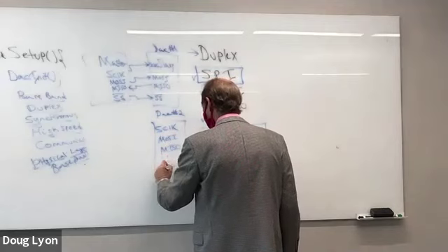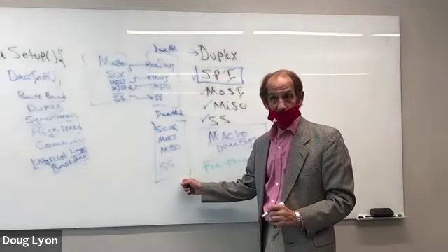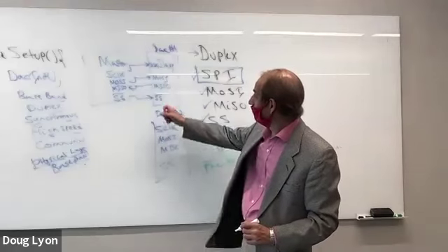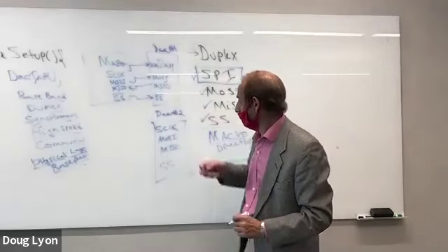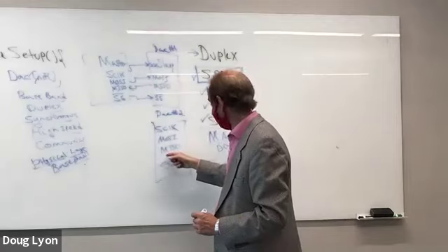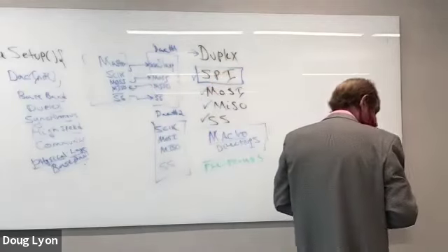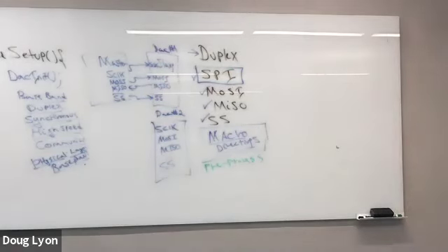and serial select. And the serial clock that this device uses is going to be the same as the serial clock that this device uses. And the MOSI that it uses will be the same MOSI that this uses. And the MISO will be the same MISO that this uses. How do I differentiate?